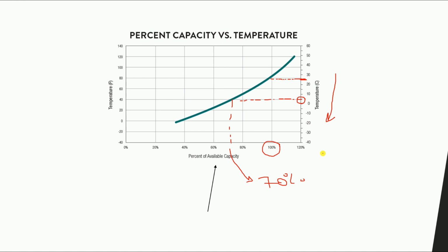So if you are operating at a temperature less than 25 Celsius degree and going down, you need to look at this curve, which you will find in the datasheet or the specs of the battery. It will help you select the correct one. This is called the temperature compensation correction factor. So it is a correction factor. You need to make sure to add this in your own calculations if the temperature of the location decreased a lot below 25 Celsius degree. So you'll find that the lower the temperature, the lower the ampere hours that can be taken from the battery.